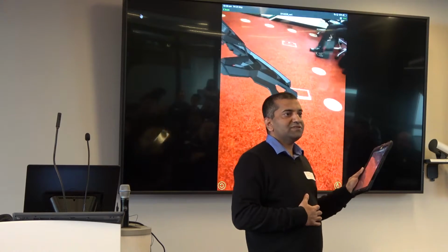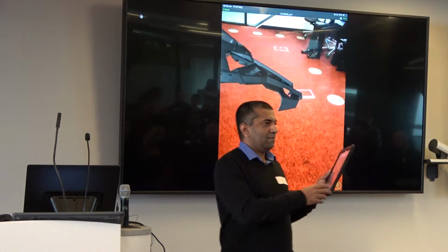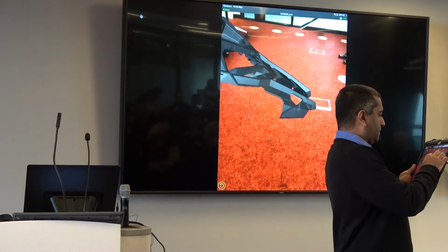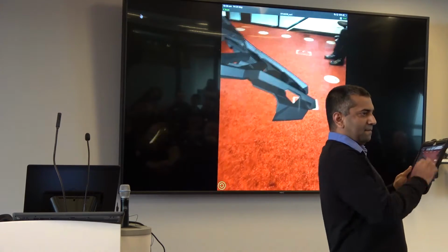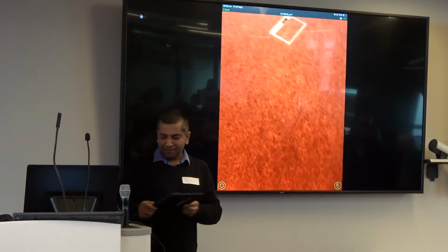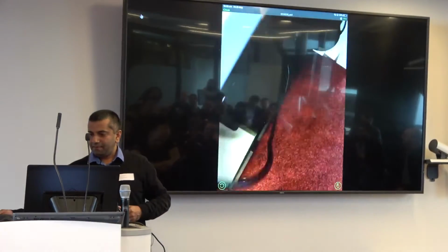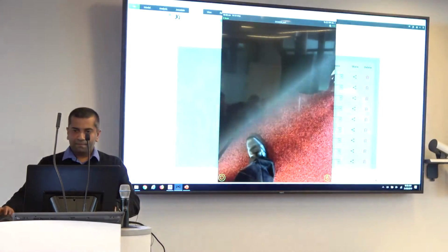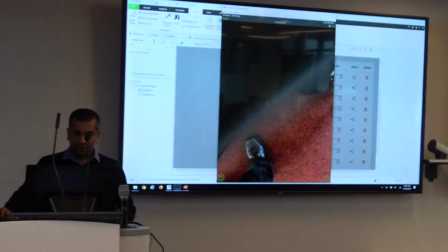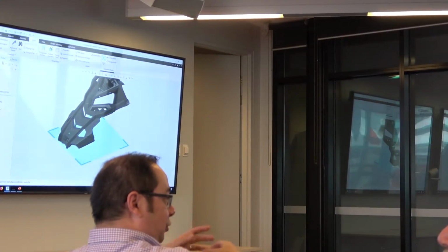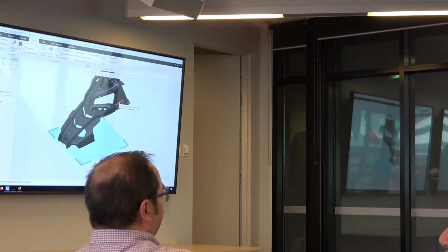Any questions? It's really a way of having, say, a suitcase where it's closed and open, where they can actually interact with it. So basically the Creo AR Design Share publishing is whatever you have on the screen, that's what it publishes. So you need to have one experience with it closed and another experience with it open. If you want to have one where you could have animation or turning things on or off or anything like that, then you need to be looking at Vuforia Studio for that.